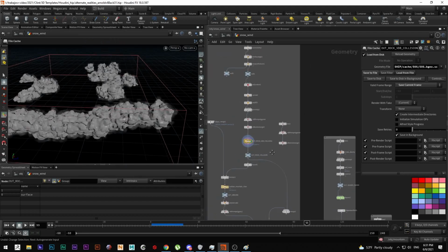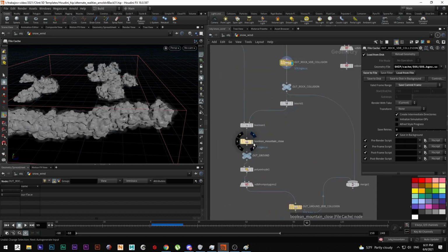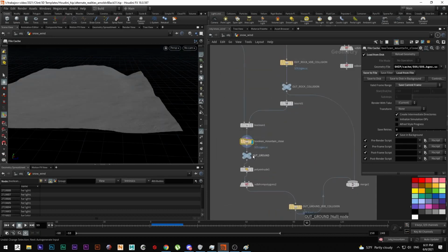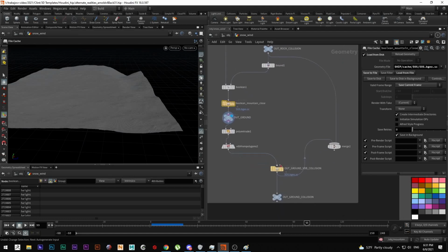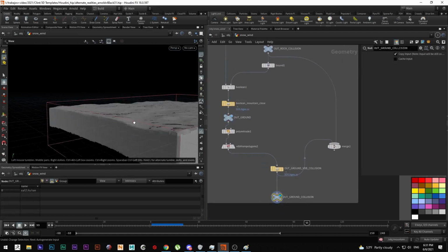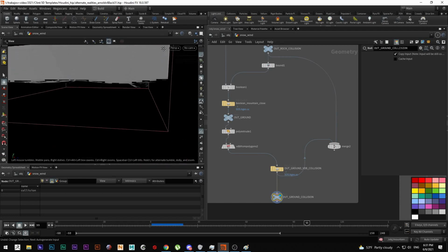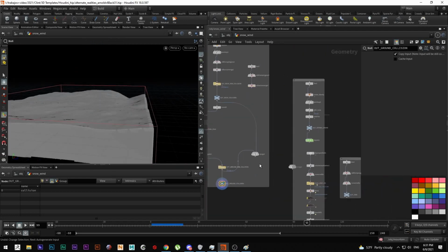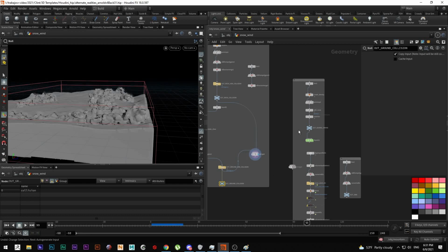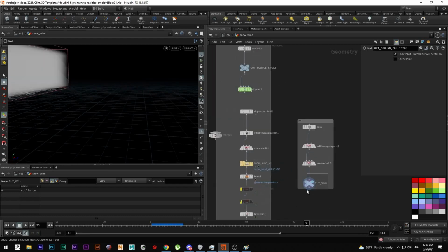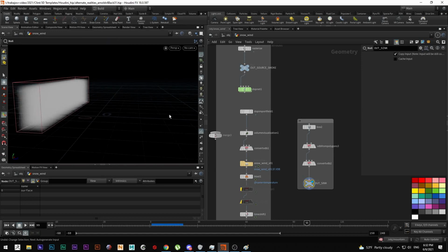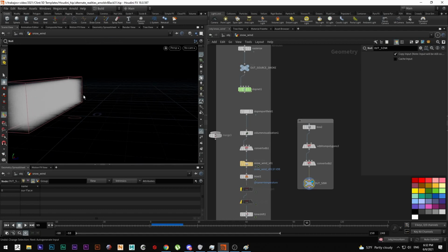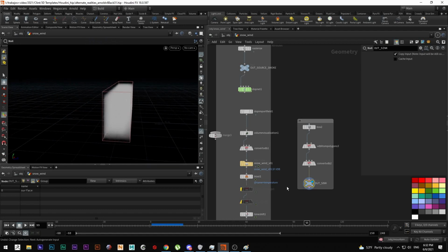And you also have, let me see, the collision of the ground. It's a polyextrude with VDB. I didn't add any velocity, so I have the collision, so the smoke doesn't go through it. It is the same result. These are both mixed. And I have a sink. A sink field basically deletes the density. If there is smoke coming through here, it gets deleted here.